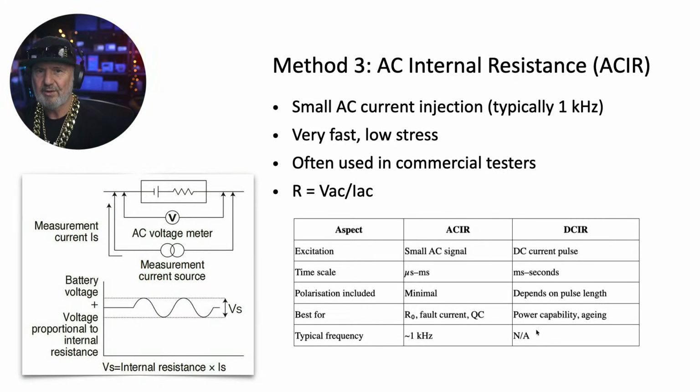So we're not talking 230 volts AC. We're talking a frequency generator that can generate a small current, so around about 1 kilohertz. There's a little diagram of it, and you will need an oscilloscope to be able to measure that offset voltage because it's an AC applied to a DC source, and so there'll be a DC offset. Yeah, it's quite complicated, isn't it?